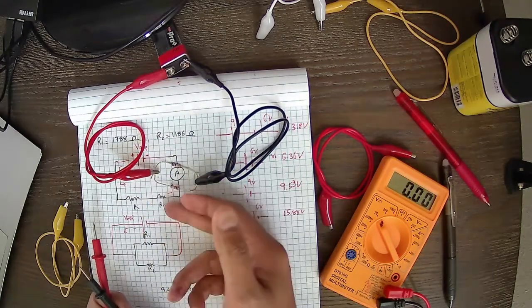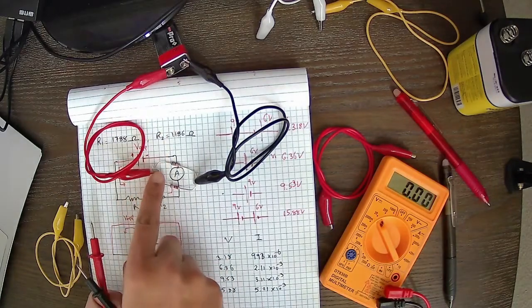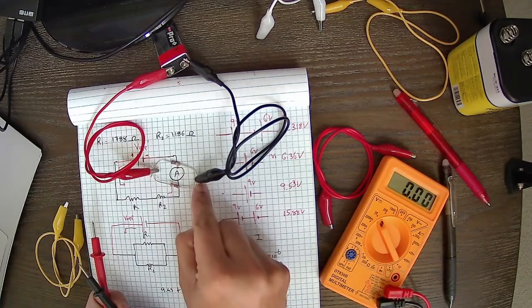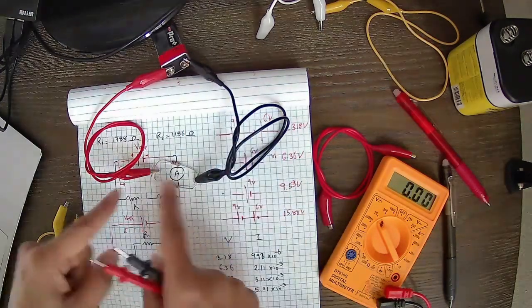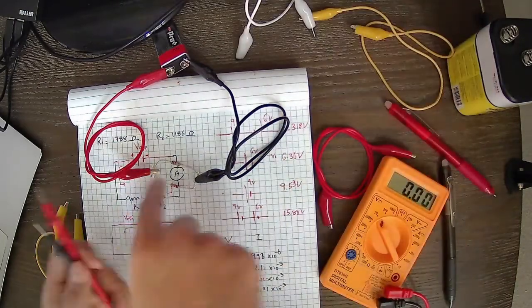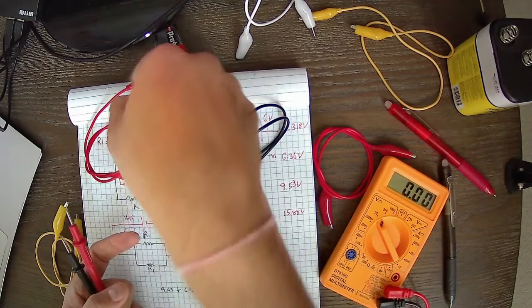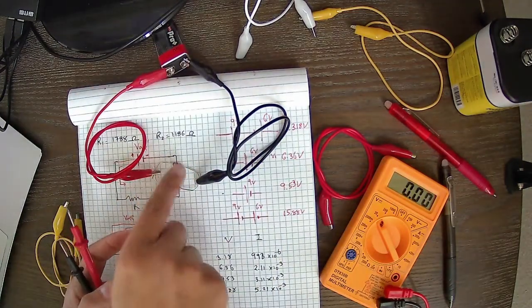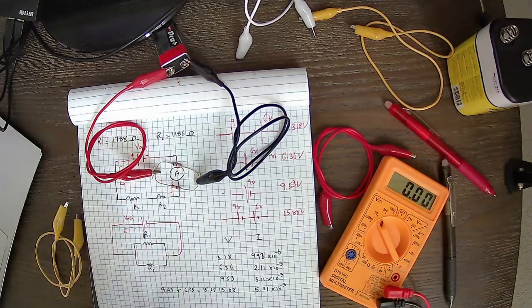The current is different. Whatever current is entering gets split at this junction into I1 and I2, and then they meet again at this end and go out. Using wires, you can make it a little more flexible, so you can measure the current going in, the current going out, and through 1 and 2, and verify that too.